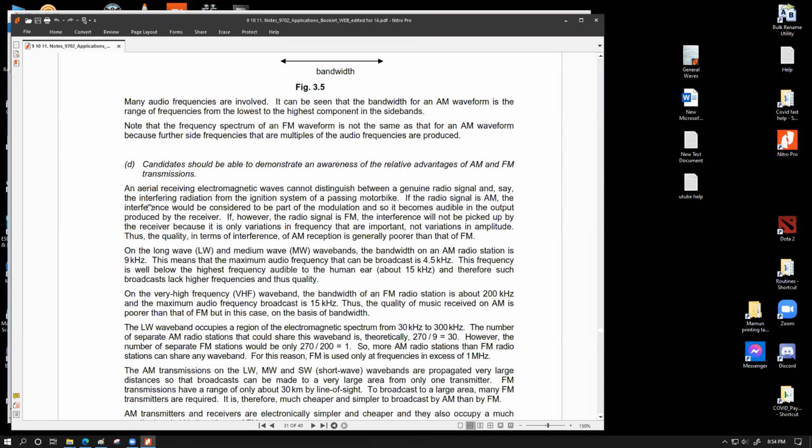The first paragraph said that AM picks up noise from the communication channel more effectively, which cannot be distinguished on the receiving end, which means any noise picked up in the communication channel will be played as output on the output side, whereas FM might pick up noise which is going to affect the amplitude, but since amplitude variation is not the thing that we're going to judge, we're going to judge the frequency variation.